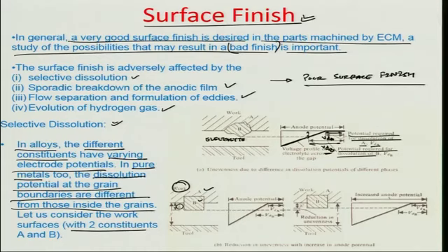Okay. So, therefore, the phase B would start dissolving much earlier, probably from this point, in comparison to the phase A, and therefore, there is a tendency of surface roughness to happen, because B is getting eroded at a much different interelectrode gap in comparison to the phase A. So, A and B would not really rhyme with each other as far as the equipotential surfaces go.